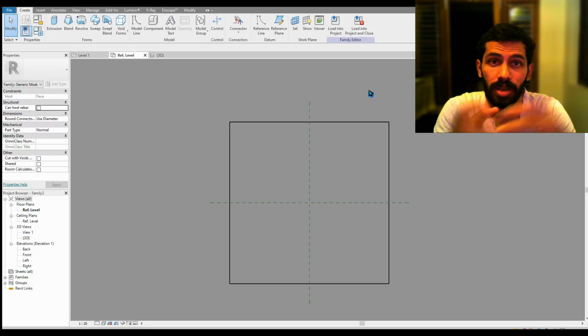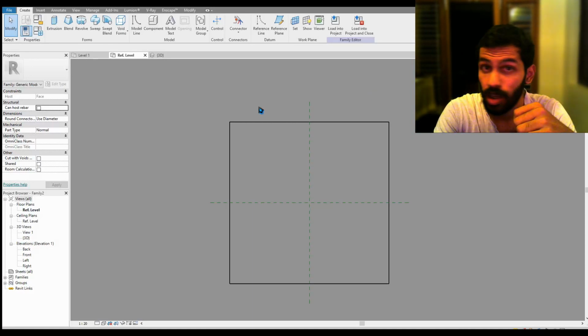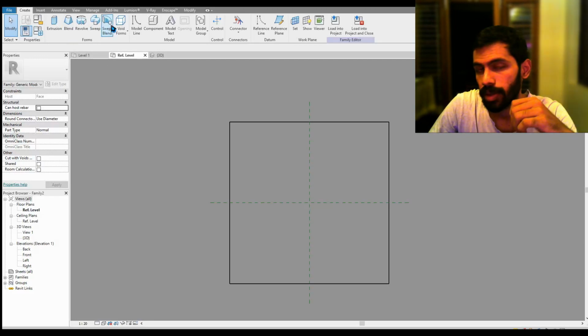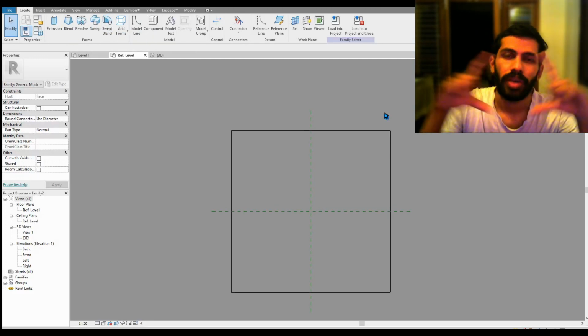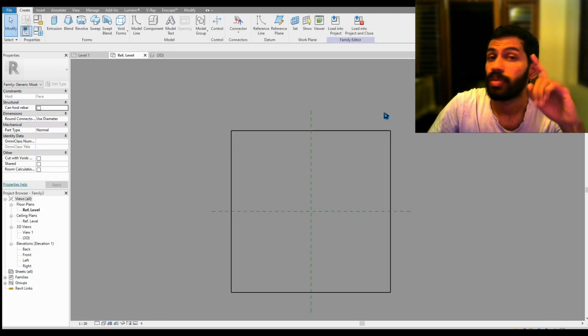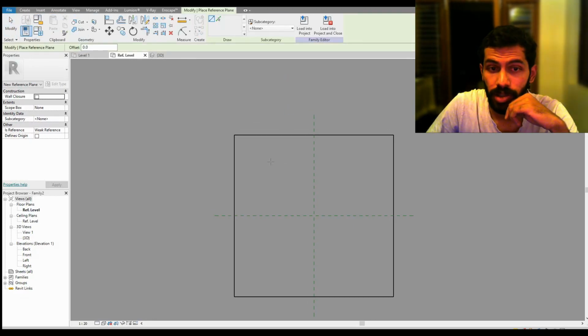These parameters can be controlled either from Edit Type or the Properties palette, just like changing the width of a door. And the last point is that we can draw any object by making use of the inbuilt forms in Revit Architecture. So let's try to create that. I would like to have a rectangular panel with width as its parameter. The first point is creating the reference plane. So the reference plane is here.